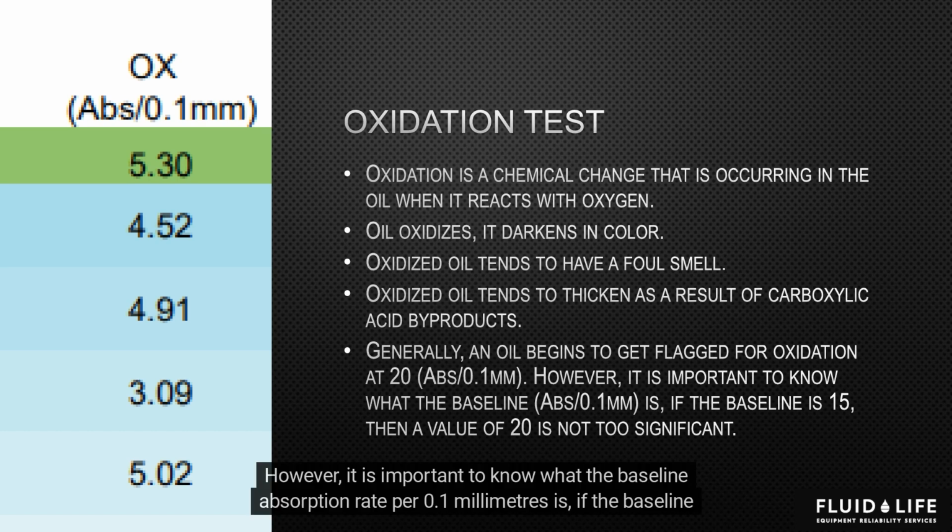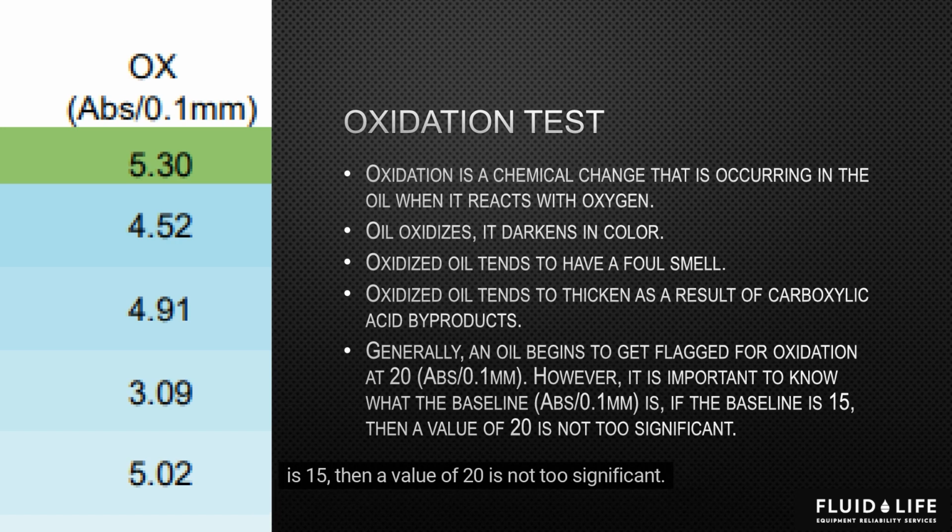However, it is important to know what the baseline absorption rate per 0.1 millimeters is. If the baseline is 15, then a value of 20 is not too significant. For the most part, new oils are under 10. Turbine oils tend to be lower at 5 or under.